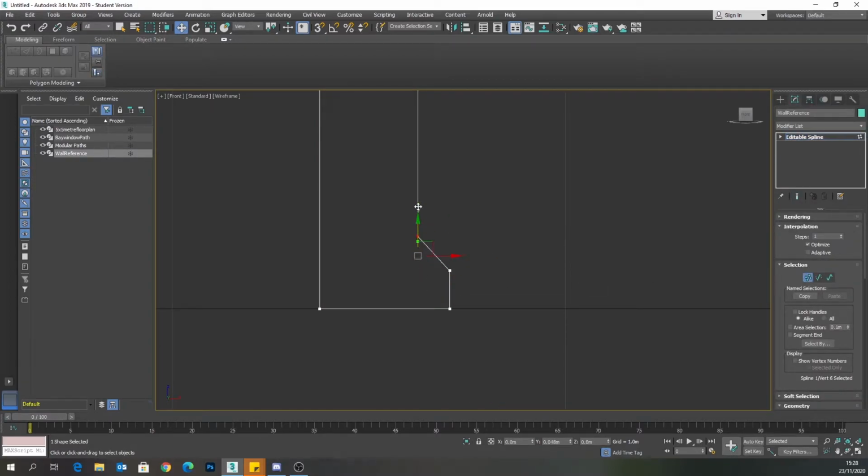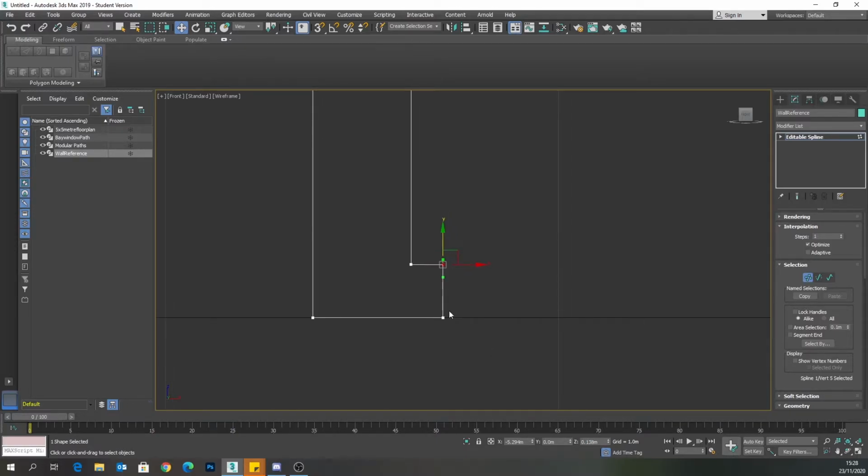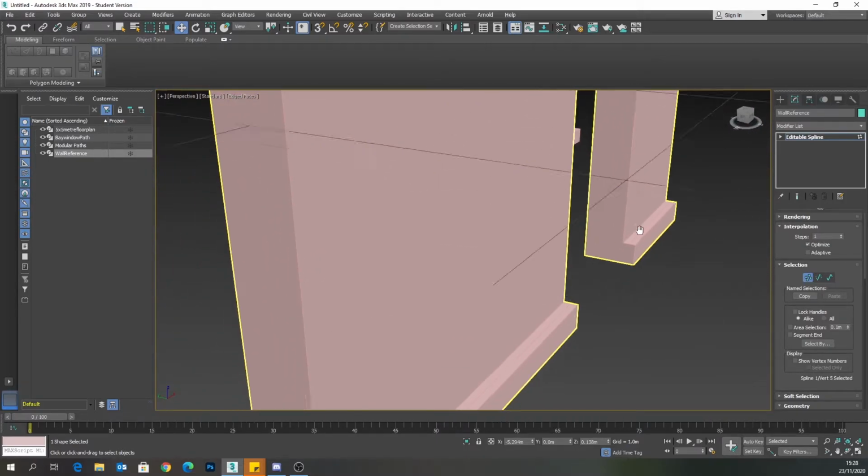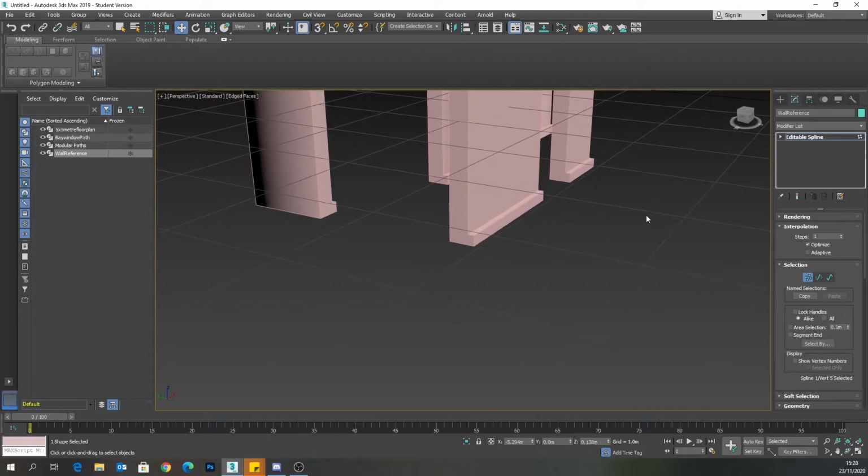So at this stage, all I'm going to do is align things so that they're fully square. I'm just looking at the axis points here, and I can copy and paste the numbers or type them in so that they're the same. It's just finding out which axis point's controlling what with this. So I'm going to move that one to there. So Control C on the other one, and then Control V on that to copy it in that coordinate. And now we can see it's a flat surface on top of the skirting board.